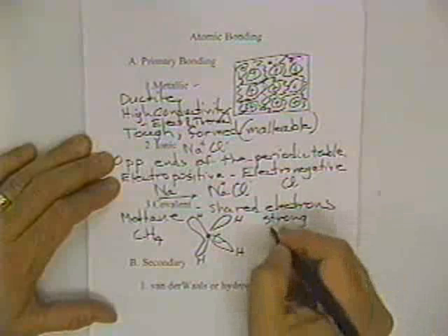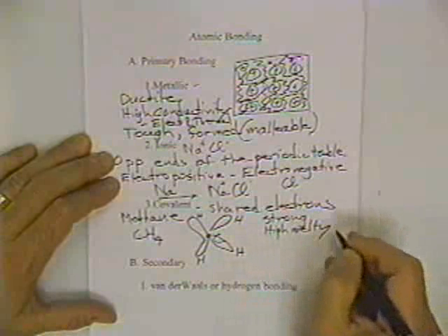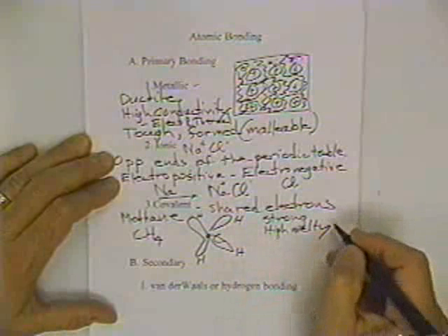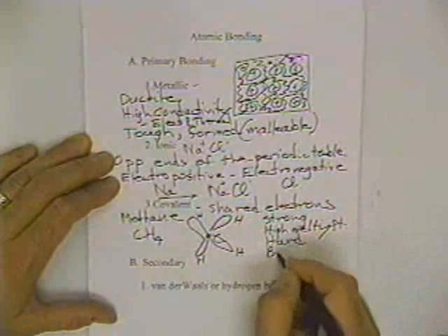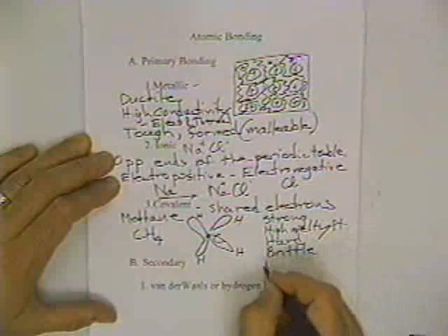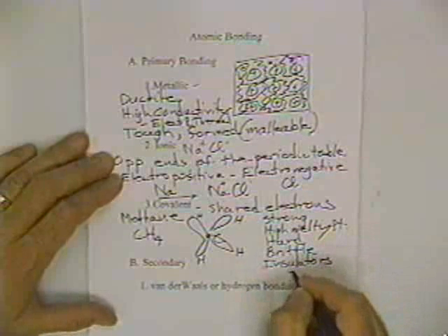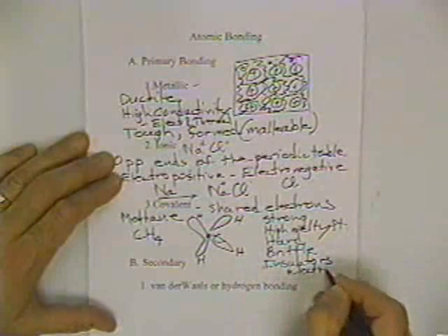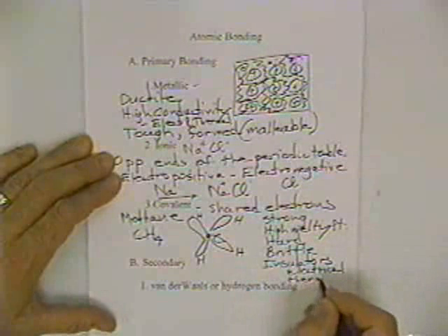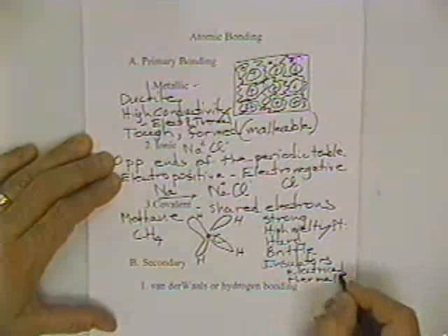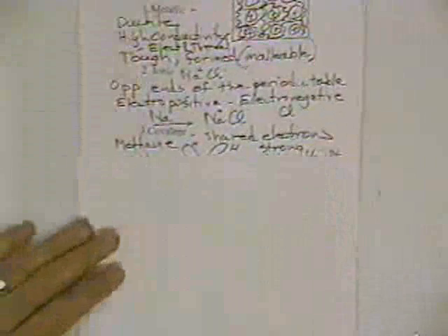We would have very high melting point materials. The hardest material is covalently bonded, that would be diamond. High melting points. They are hard, they are brittle, and they are insulators. Now this is an interesting category. All of them are electrical insulators, and most are thermal insulators. And we might just put a little footnote to ourselves there, because